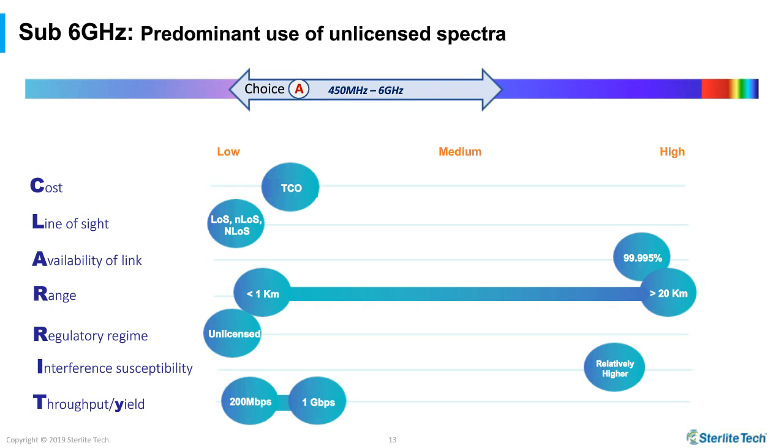And how you design the link becomes very critical, especially in urban, suburban environments where Wi-Fi is prevalent. And the throughput, we can go anywhere between multiple 100 megabits to all the way up to 1 gigabit. And some of the attributes of the technologies are adaptive modulation and MIMO. You have some of the benefits of these that give you the improvement in capacity.